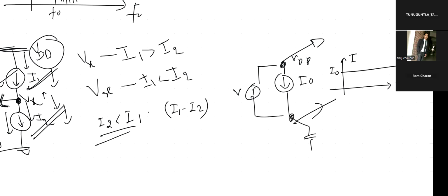So it has no meaning with this node voltage, because whatever difference comes across it, it has no effect. You can see this simply in RC circuits. When we pump some I naught, we can put VDD here also. Like this is my capacitor, this is my resistor. This question usually comes up in RC question sections. Whatever you connect here, it doesn't matter. You can connect VDD or ground. Because you're pumping a constant ideal current into this node, the capacitor voltage will increase, with no control on it.